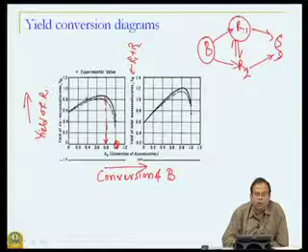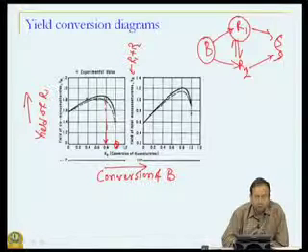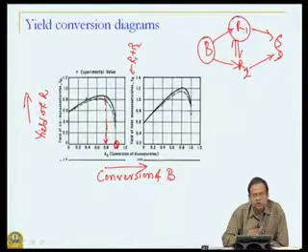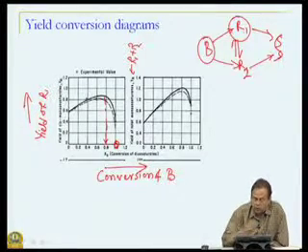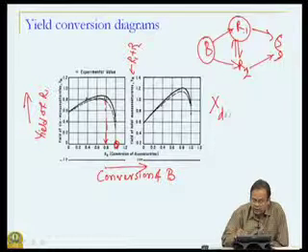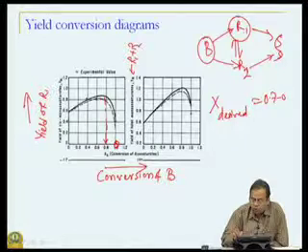So, our reactor design: the desired conversion is not 100% conversion of B, but a certain 80% or 70%, depending on whatever may be the true results. So, that is point number 1. In other words, our x desired is in the range of 0.7 to 0.8.